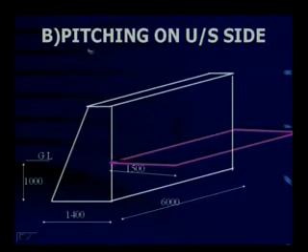It is excavation for pitching on the upstream side. As I have told you, this is the 3-dimensional view of the apron on the upstream side. Do you remember that the width of the apron is 1500 mm? Fine. And now see here, this is the area where pitching is to be done. Pitching is nothing but laying of stones along this area. Is it okay? Now, you need to make an excavation here along the apron on the upstream side.